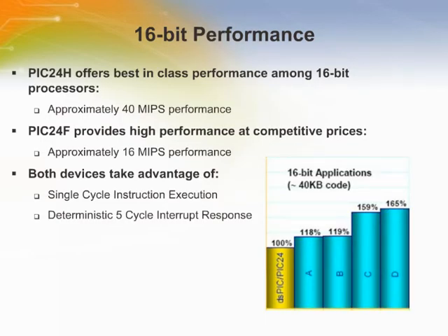Using internal benchmarks based on industry standards and internal application code, Microchip's entry-level PIC24 family executes at 16 MHz with about 14 million instructions per second throughput, showing an advantage of the RISC architecture's single-cycle instruction execution. The graph shows the results of compiling C code with various C compilers for a number of processors.